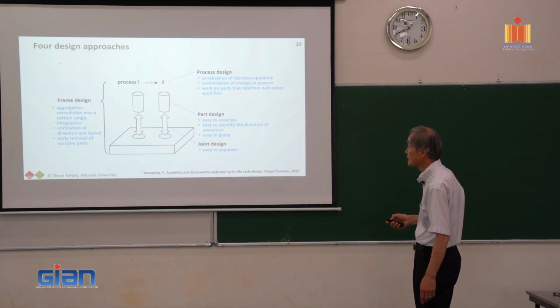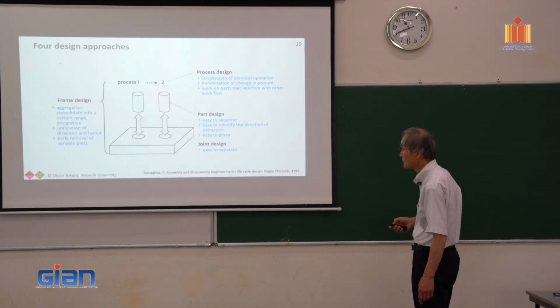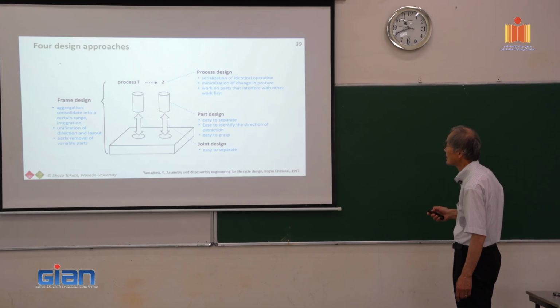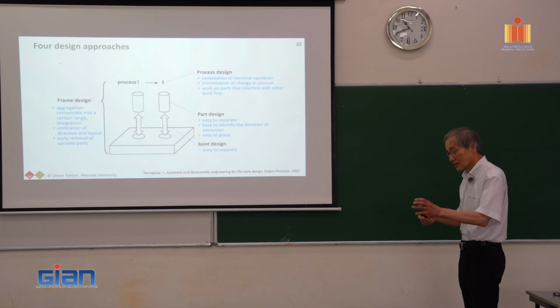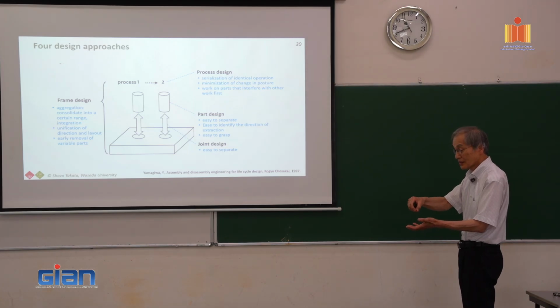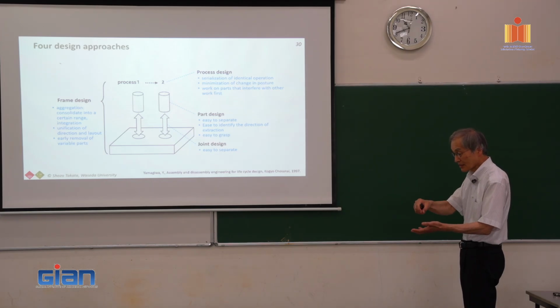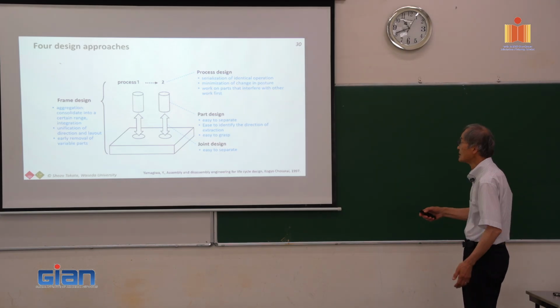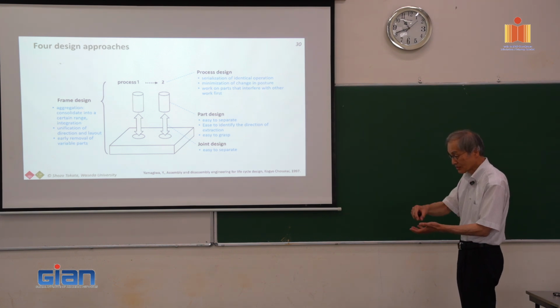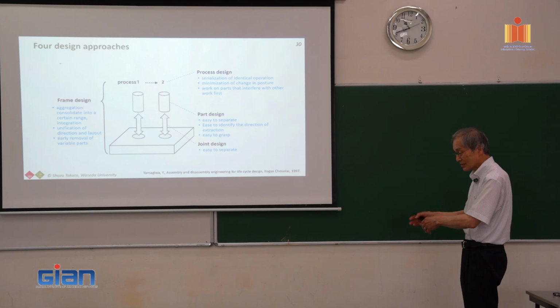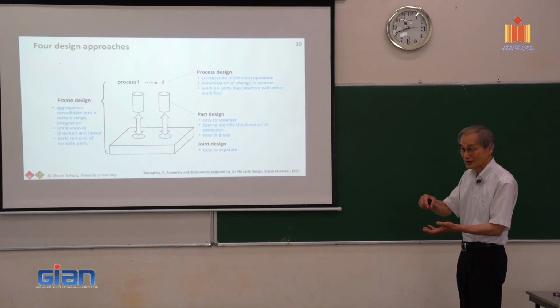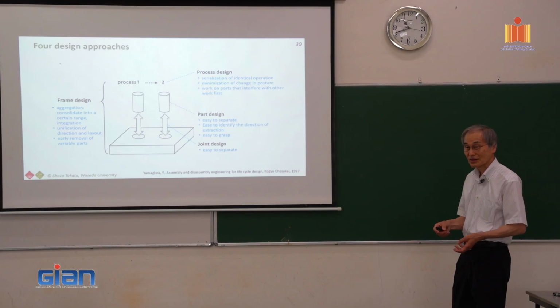So the frame design means aggregation, unification of direction and layout, early removal of variable parts. And process design, serialization of identical operation. If you unscrew or screw, then you need to do the same operation altogether, not screw with one tool, then change to another tool, then again the screwdriver and so on. That is not an efficient way.